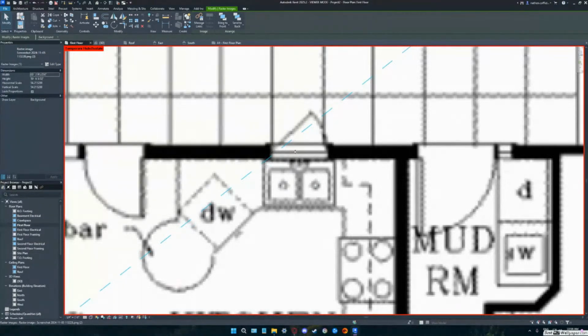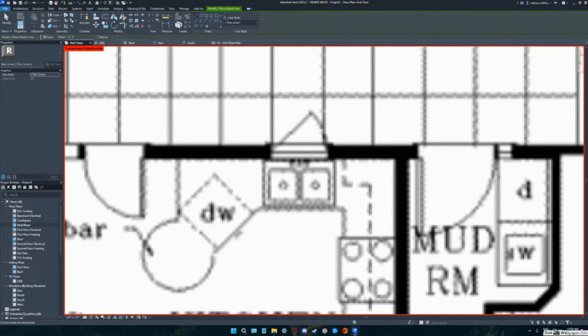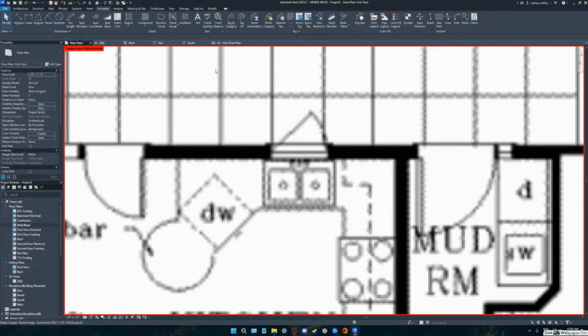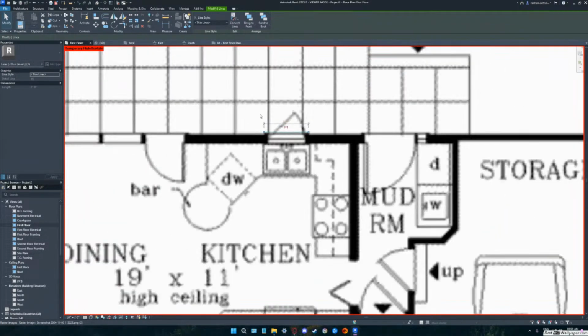This is where I'm saying that you could draw a line, go to annotate, draw the detail line from one edge to the other. Perfect. Now hit escape 2 times. Now pick on the line and pick on the dimension above that. Yep. Now you could say Control C to copy that dimension out so you don't have to type it. And now you know you need to make a 2'8" window. Does that make sense? Yeah.